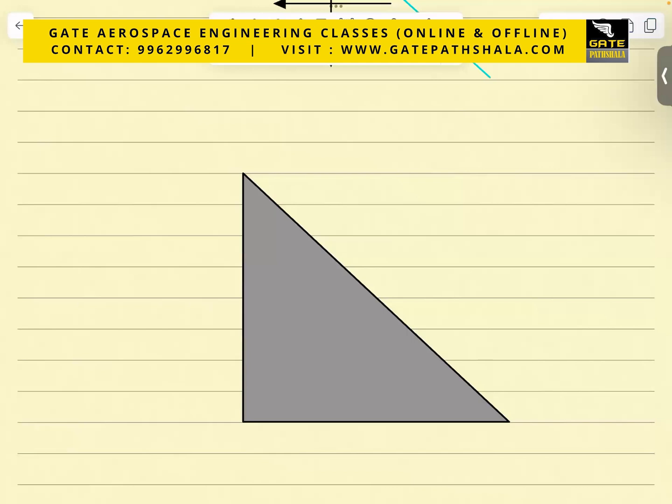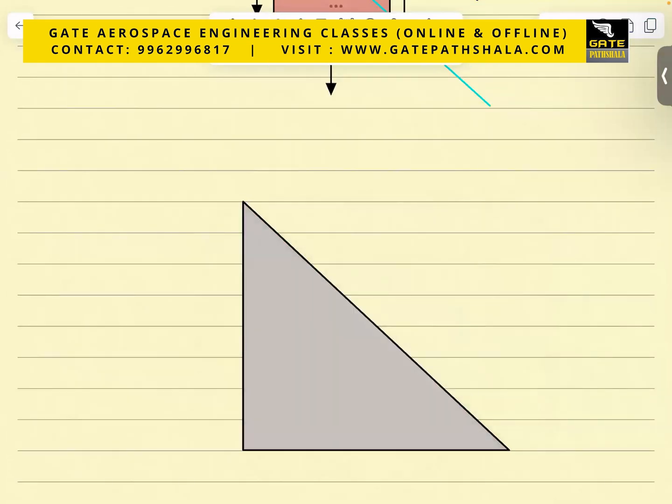Draw this, everyone. This will be fine. Draw this. Now tell me, this is the plane I cut. So what are the stresses that are going to act on that plane? Come on. Normal stress and there will be shear stress. Agree? Guys? Yes, sir. So this is your sigma n and this is your tau. We are going to find what these stresses are, sigma n and tau.